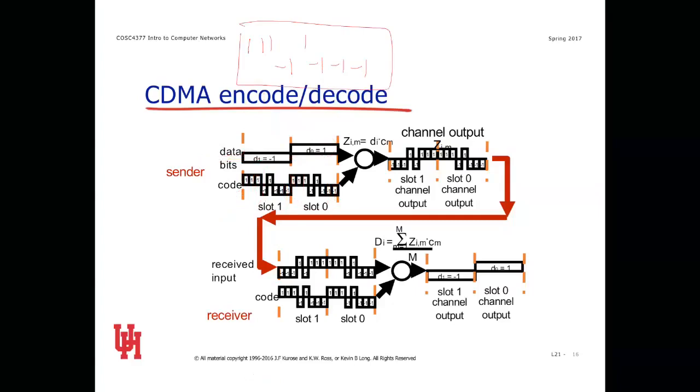So when I see that somebody wants to send a 1 for data, then I leave this alone, because this block times 1 equals itself, just like every other number. Any number times 1 equals itself. So we're going to use this for this sequence. The other value I can have is a -1. Anything times a -1 is the inverse of itself. So this is the same chipping sequence and the inverse of the chipping sequence. Are we together so far?